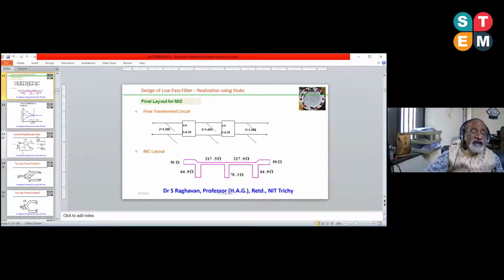See, this is a small example. You take a filter, either in a microstrip line or a strip line. This will be the profile. In one case it is epsilon effective, in the other case it's epsilon naught. Each length is lambda g by 8. If you remember lambda g by 8, what formula do you need? People might have seen this, but what I am presenting is a consolidated way. If you know everything in terms of lambda g, 50% of the design of any component is over.